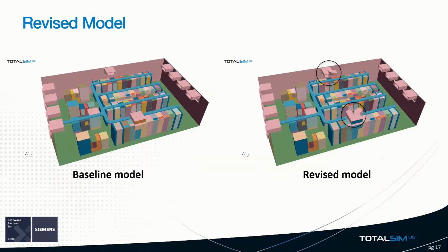With warm air trapped in the north and southeast corners, one way we can optimize the design is to modify the north and south split units with bifurcated ducts. This would have a dedicated duct supplying cool airflow into these corners. Everything else remained the same in the model. All the heat load setup remained the same.